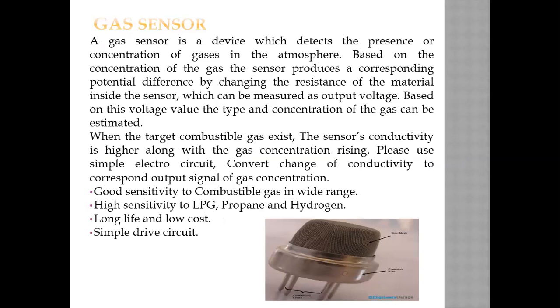So this has been very important because of what type of gas has been used here. It is inflammable. Suppose I have H2S gas, or I have toxic gases coming out. So I have to sense its intensity, so that I know how far it can affect my atmosphere. Therefore, one has to know the sensor conductivity, which is higher along with gas concentration rising. So the concentration of the gas can be measured, so that I am able to find out its intensity and its impact on the other environments.